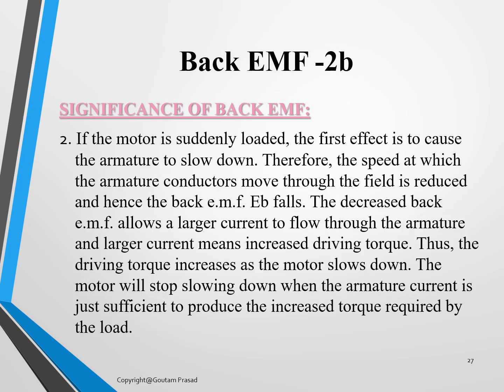Now think of a situation. If the motor is suddenly loaded, the first effect is to cause the armature to slow down. The speed of the motor will slow down because of heavy loading, and therefore the speed at which the armature conductors move through the field is reduced, and hence the back EMF falls.